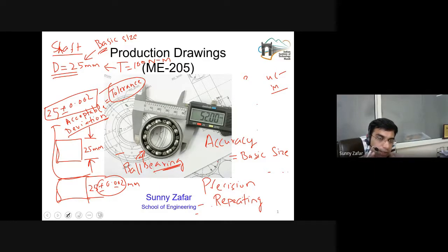The cost of production of any product will be higher. So there is always an optimum tolerance level which is not too tight, because if you create very tight tolerances, the cost of production will be too high, and then the cost of the product will also be very high, and the customer taking that product is also paying a higher cost. But tighter tolerance may not always imply improved performance. Generally a satisfactory level of performance may be achieved by an okay type of tolerance product.